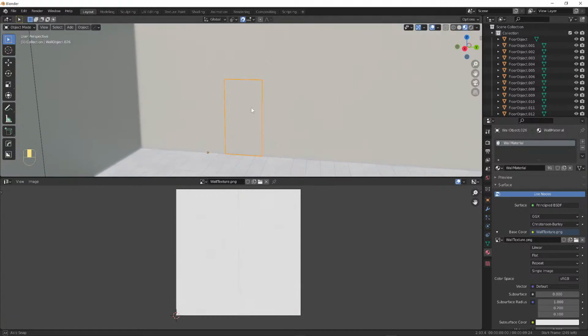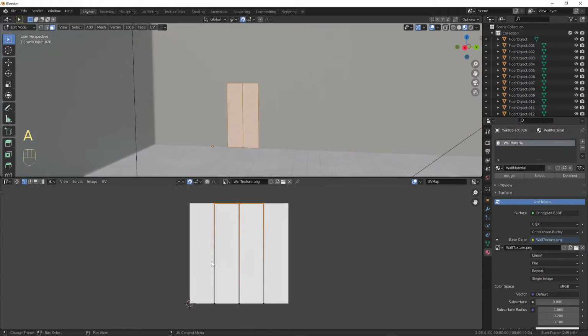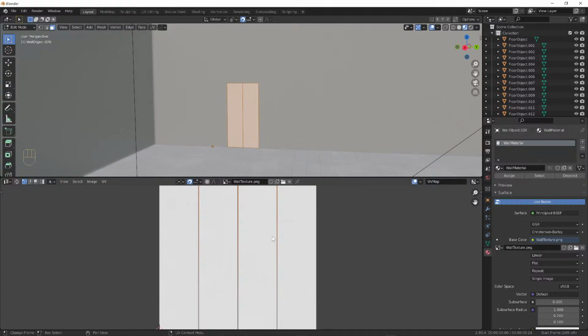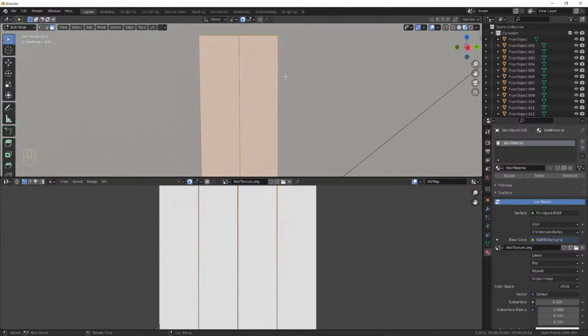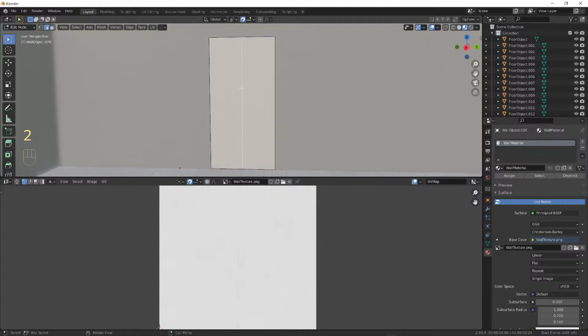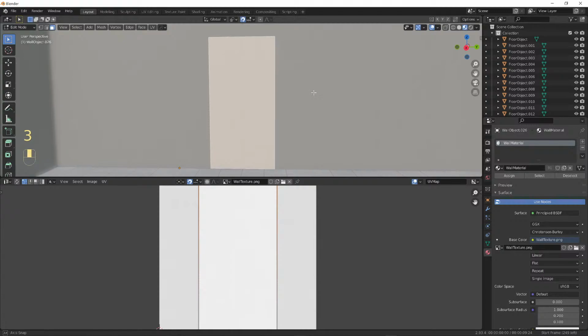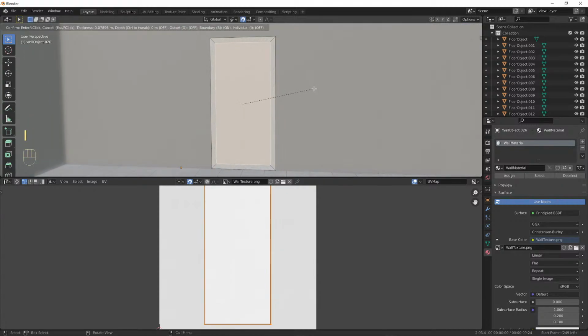I want to have a door frame and everything like that, but if I just select this here, see I have this wireframe, so I could draw in my door texture here, and that would work. And I would want to also have some kind of baseboard. What I'm going to do, I'm just going to cheat a little bit. I'm going to make my door and door frame from this. So first I'll delete this center edge, or dissolve it. I'll select this center loop. I'll press X here, dissolve edges, select this whole face, press I to inset slightly.